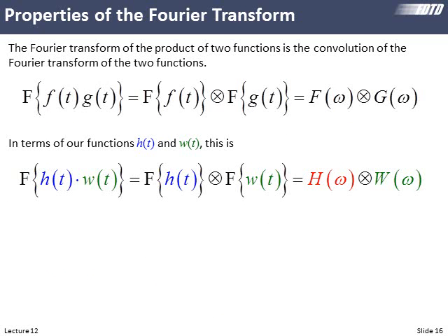Let's think about this. We have two time domain functions. We have our infinite impulse response. That's what we would get if we really did have a finite difference time domain simulation that simulated out to infinity time. But we multiply it by a window function. So we have this multiplication. Remember, if we have a multiplication of two functions and then Fourier transform that, that's just like we Fourier transformed the two functions independently and then convolved them in the frequency domain.